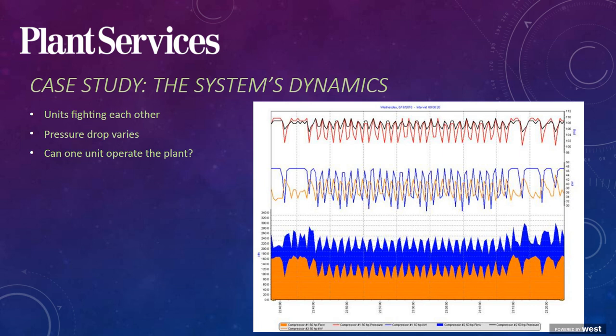And most often we saw both 1 and 2 compressors loaded to maintain plant pressure. The available compressor supply is significantly exceeding the compressed air demand. And based on the measured flow profile that we're seeing during the test, compressor 1 was capable of meeting the average demand without assistance from number 2, but was not capable of meeting the peak demand.